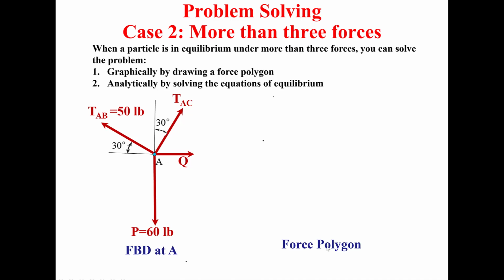Now the next step is what? To draw the force polygon. This is the graphical solution, the first solution. I'm going to start with the forces we know. Now I start with the first one; this is the beginning point. I'm going to call it O.